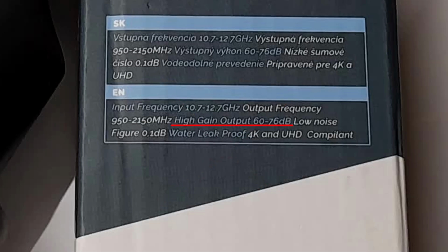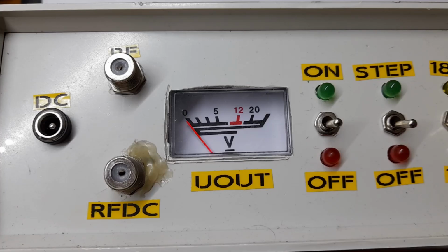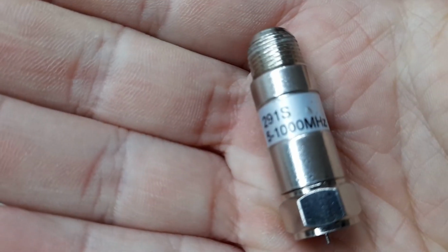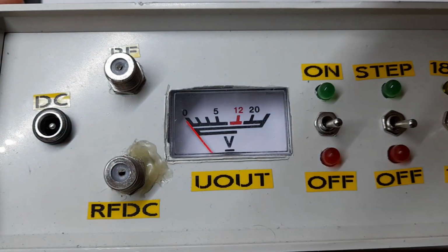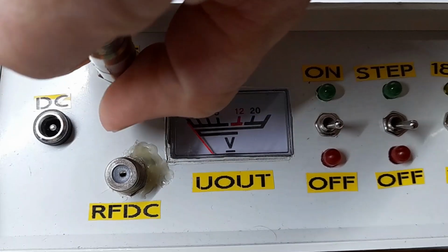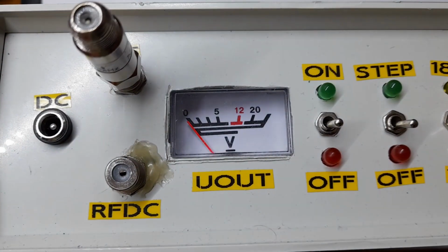LNBs usually have a very high gain amplifier on the IF output, which means that it may be advisable to use an attenuator when connecting it to an SDR. I'm going to use a 16 dB attenuator, as that is the only one I have, and put it on the RF port of the bias T, so the direct current isn't going through it. I will however mention that up until now I pretty much never used it and haven't experienced any issues, but I cannot guarantee that all LNBs will be the same.